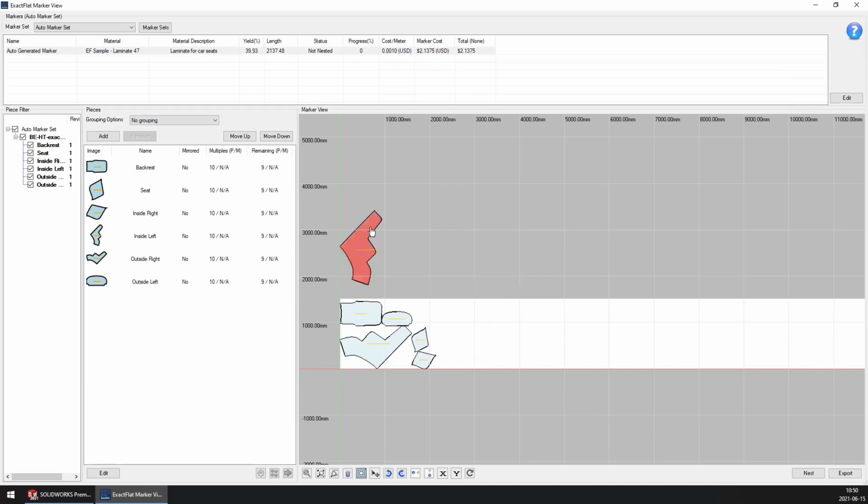So for that reason here, I can manually rotate my piece and I can drag it on and it will fit. But the automatic rotation is being done to try and produce a pattern piece that has a minimum height configuration. So that's why the placement for that piece failed. We'll look a bit more at that option as we explore the placement options here, but for now I just wanted to show the effects of the box packing.